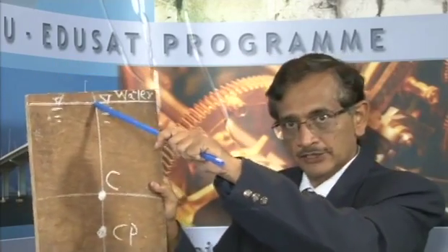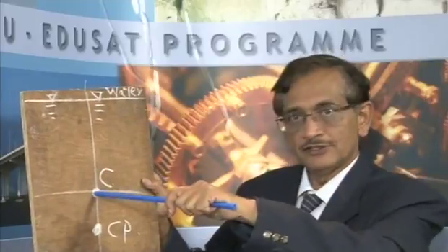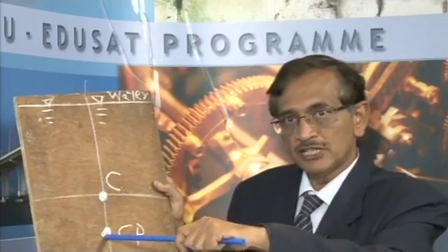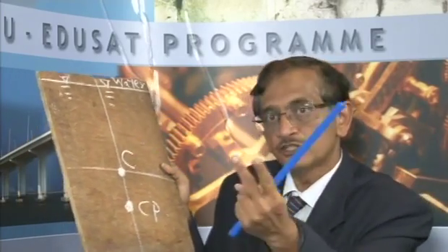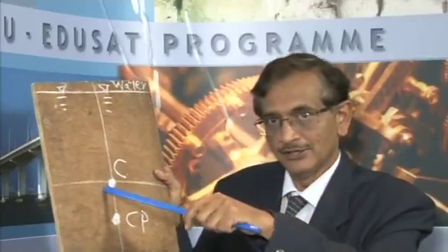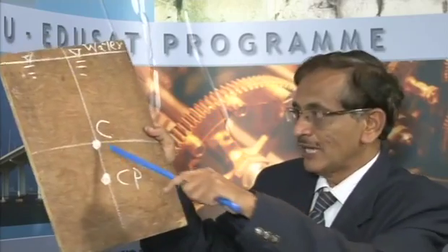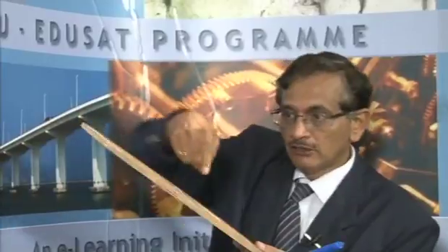For a vertical plate like this, the centroid is at 10 centimeter from the water level, you can see water level, 10 centimeter. Center of pressure is at 12 centimeter, it means 2 centimeter below the centroid. When I make it incline at any angle, say 30 degree, 60 degree, 45 degree, 10 degree, it will lie between C and Cp. It means it will lie between 10 centimeter to 12 centimeter. So, the answer will be between 10 to 12 only, right. Then how it depends on the angle theta, how it depends on the moment of inertia along this line, those things we would like to see.